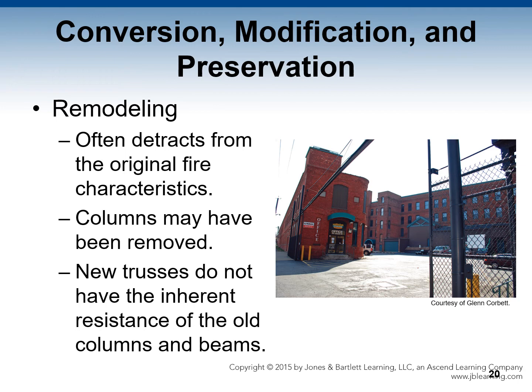Now let's talk about remodeling. Renovation often detracts from the original fire characteristics. Columns may have been replaced. New trusses do not have the inherent resistance of old columns and beams. So these are all things you should watch out for in renovated old buildings.